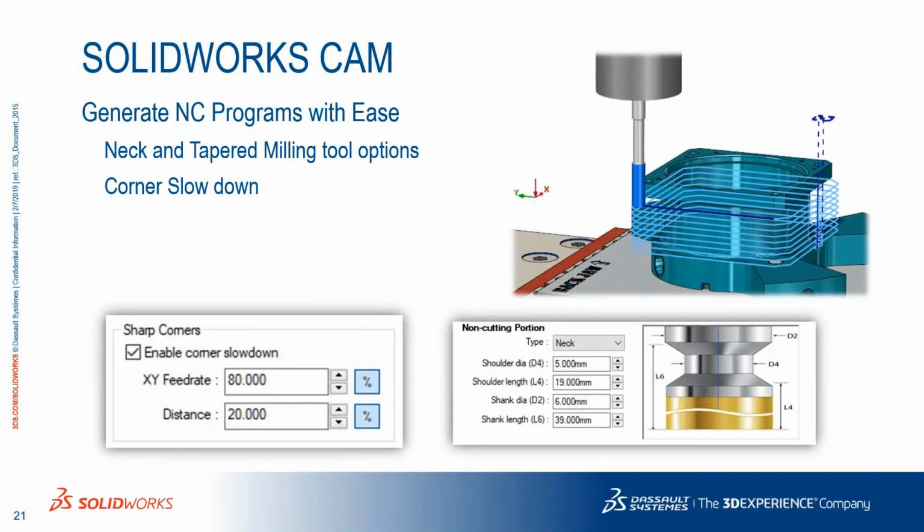And the last thing we'll take a look at is SolidWorks CAM 2019. We got a few improvements we want to take a look at there, and if you haven't seen SolidWorks CAM, it is a newer product that is powered by CamWorks. It's 2.5 axis milling, and the CAM Pro actually includes turning as well. And so 2.5 axis CAM, being able to generate CNC code within the SolidWorks interface, and this is included with every seat of SolidWorks, Standard, Pro, or Premium. Every seat of SolidWorks that's on subscription is able to use tools like SolidWorks CAM for 2.5 axis machining.